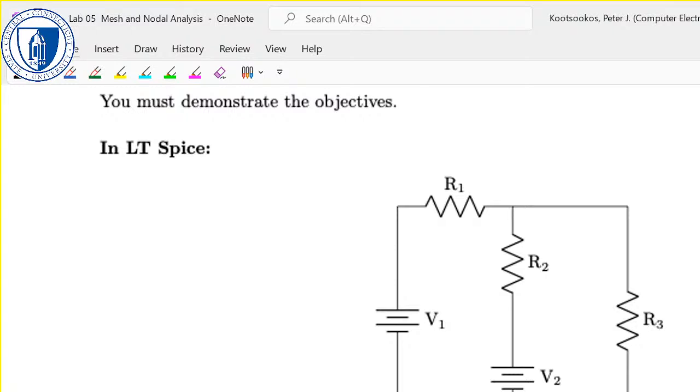You can change the voltages to channel 1 and channel 2 independently, and that's what you're going to have to do here. Previously you just used channel 1. I'd suggest using channel 1 for V1 and channel 2 for V2. Channel 1 is the second pair, channel 2 is the third pair.